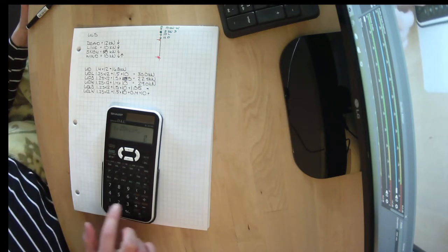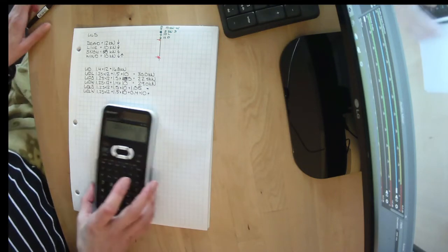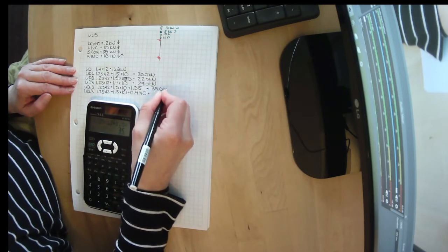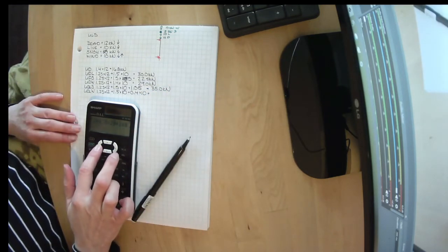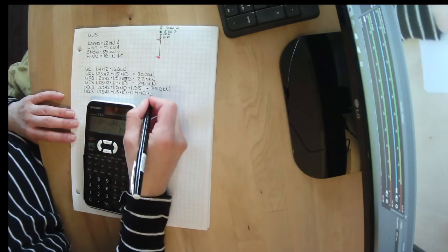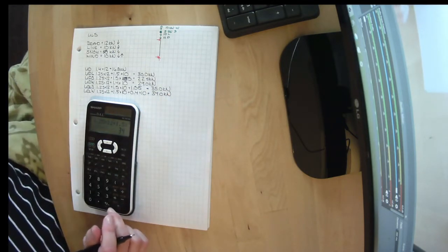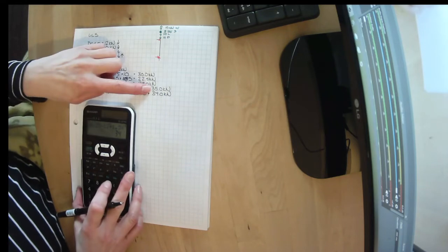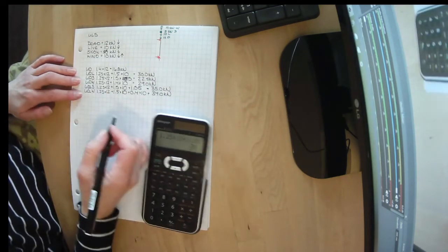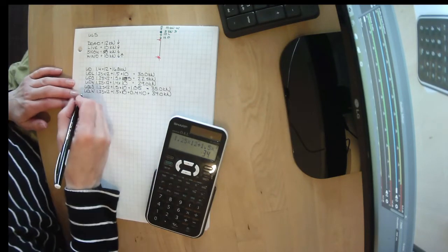1.25 times 12 plus 1.5 times 10 plus 1 times 5 gives us 35 kilonewtons, or it could be 0.4 times 10, 34 kilonewtons. So it looks like that's our new contender for the worst case load this column could possibly see. But we have to think about the other load cases as the principal load case.